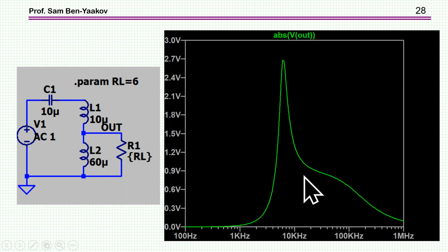It will saturate. So therefore, you can see that given these inductors in the frequency range that you would like to work at, sometimes you cannot accomplish an LLC operation, and you have to resort to a series resonant converter, which is fine, but the span of frequency will be a bit higher.